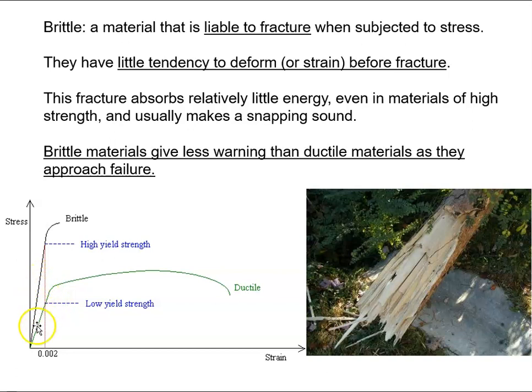So this is less stiff. It also has less strength because it does not climb up the stress axis nearly as much as this one. But this one is far more ductile. So less stiff, but more ductile. And that's often the case. Not always, but this one has permanent damage, but it lives for a long time thereafter. This is a brittle failure for wood, right?